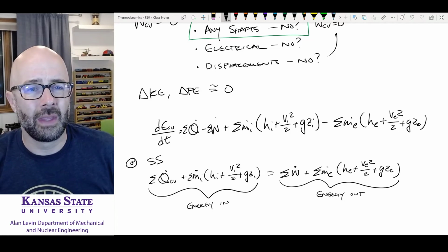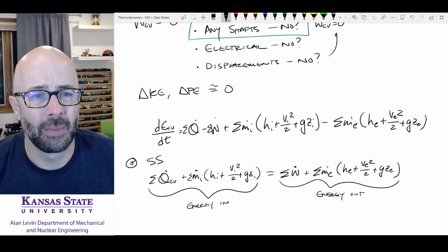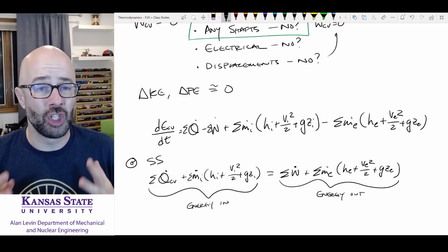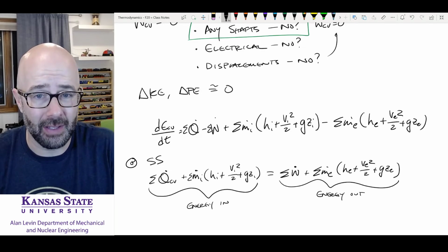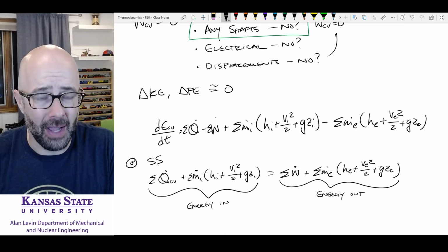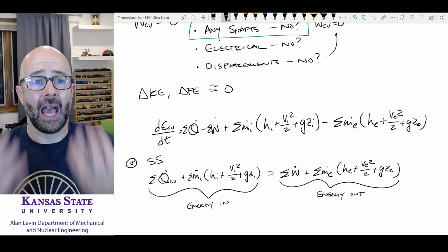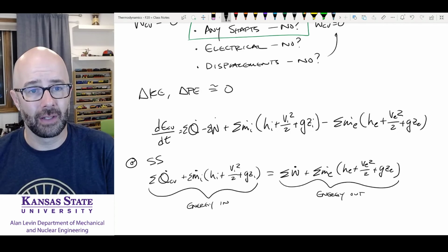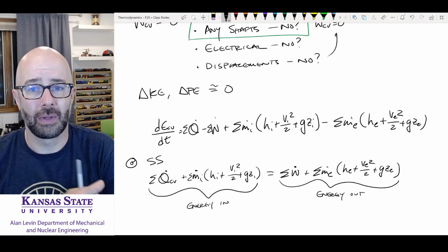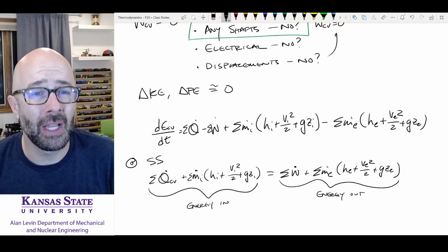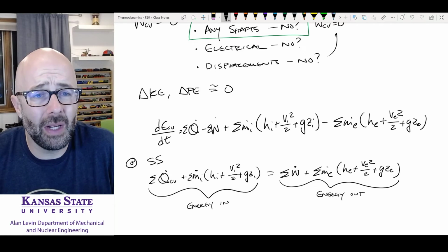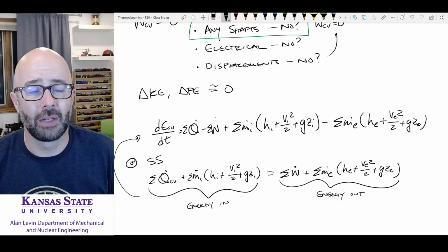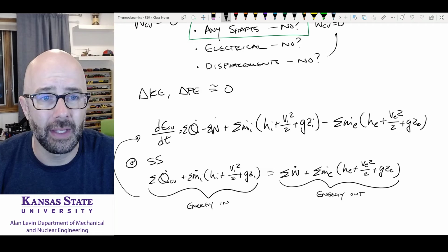Okay. The other competing textbook deals with this. They talk about the equation this way: energy in, because heat transfer in is positive, mass flow rate in is positive, and coming out we're going to have work out is positive, energy out here, as we rearrange the equation. This is how they look at the problems. It's an acceptable way to look at them. I like to go back to this original equation and just deal with it that way, but you can always go with it here.